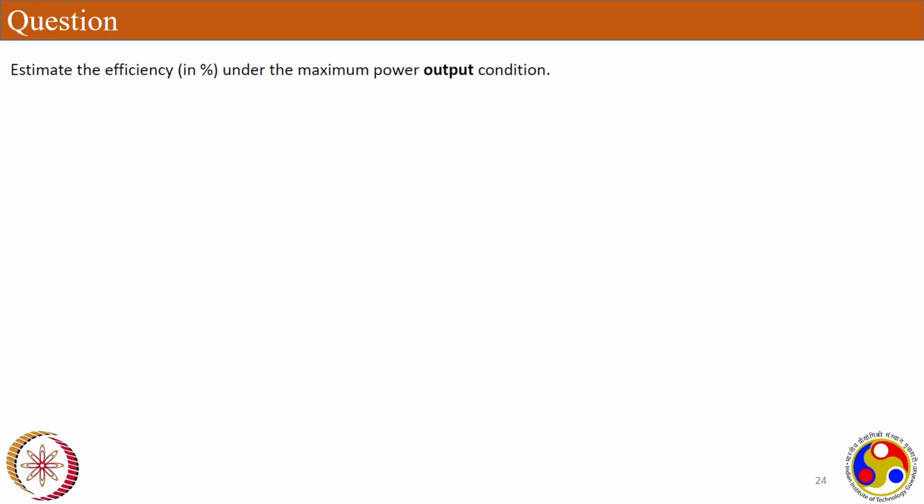You can refer to that power flow diagram which we discussed in the induction machines concept. The same thing, power flow will always be the same. There will be input power minus stator copper losses, rotor copper losses, and core losses, and rotational friction and windage losses, everything. Then you will get the shaft output power. Here, output power is nothing but the shaft power.